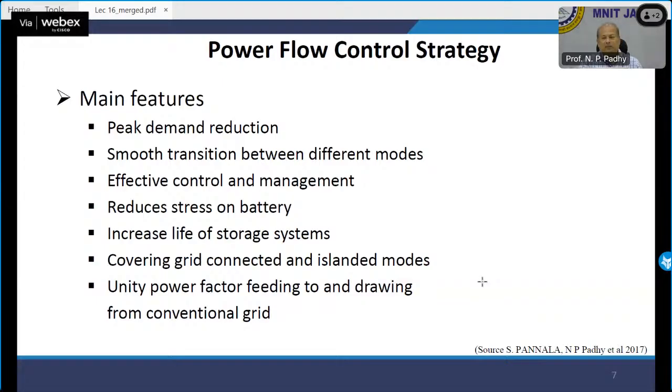If the system has a maximum percentage of renewables, and they are not operating close to unity power factor, then how do you get that reactive power requirement? If a microgrid starts drawing or giving energy at less than unity power factor, and all the microgrids do the same thing, then how will the system maintain unity power factor?